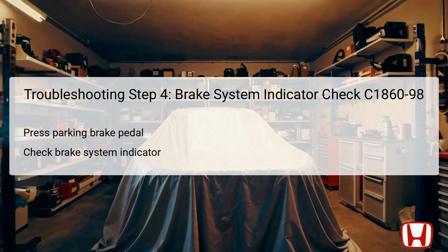However, if the indicator light fails to turn on, it suggests a potential fault within the brake system that may warrant inspection. Proper function of the brake system is crucial, as any malfunction may lead to undue stress on the AWD components, exacerbating overheating issues.